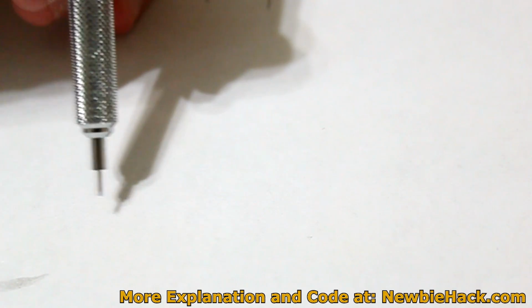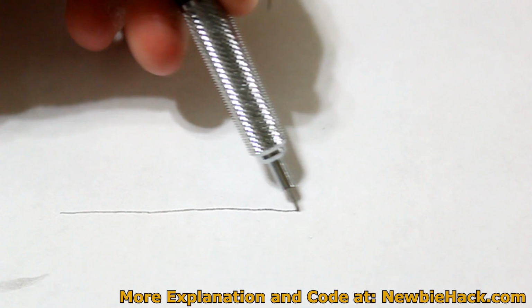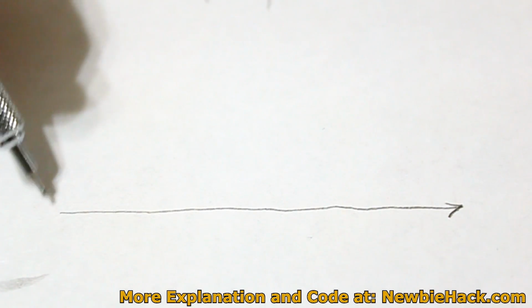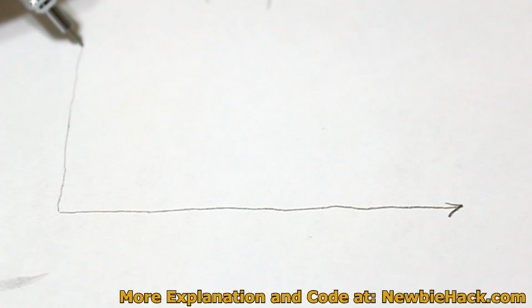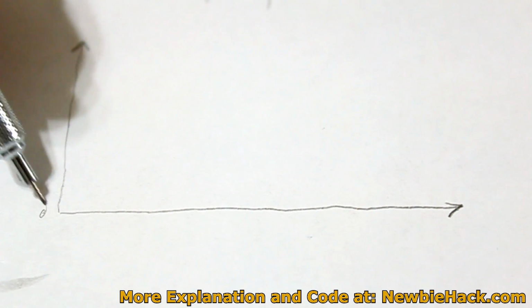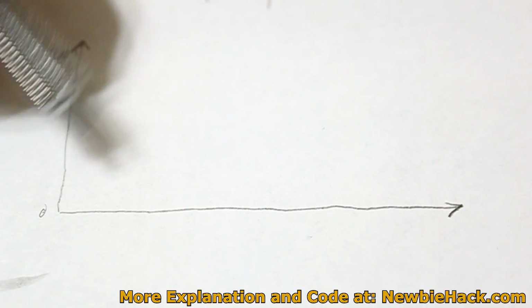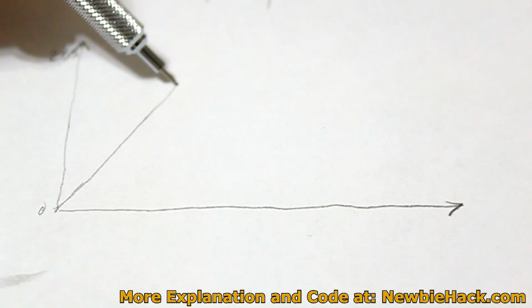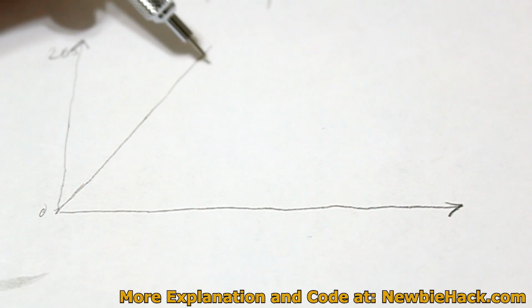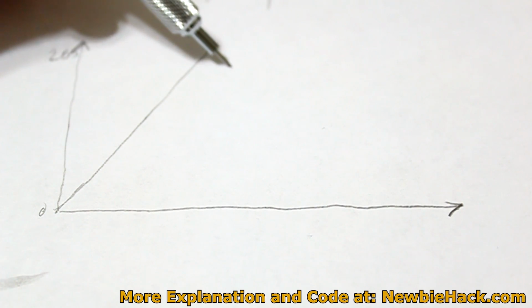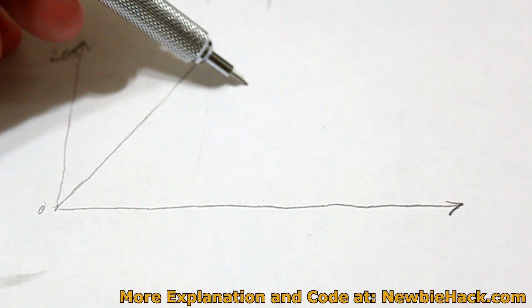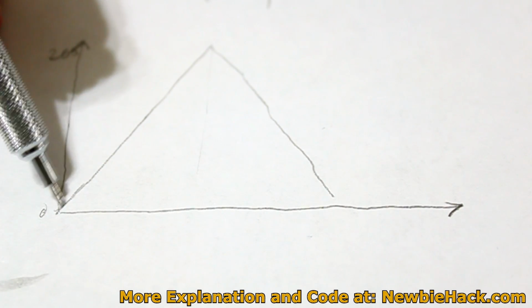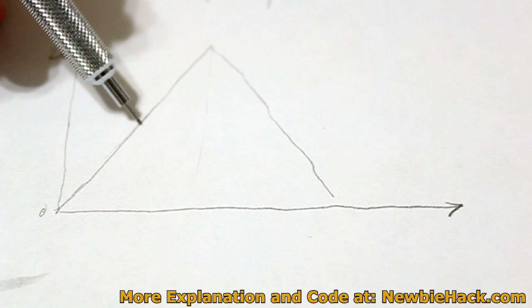So how does phase correct PWM work with microcontrollers and timers? I'll draw the time. This is time on this part of the graph, and this is counting on this part of the graph. And this will be from 0 to 255 again. And in phase correct, the counting through time goes something like this. It goes all the way to 255, and then it counts down from 255 to 0. It doesn't go straight down. It actually creates another angle like this. And you determine where on this line you're going to create the pulse.